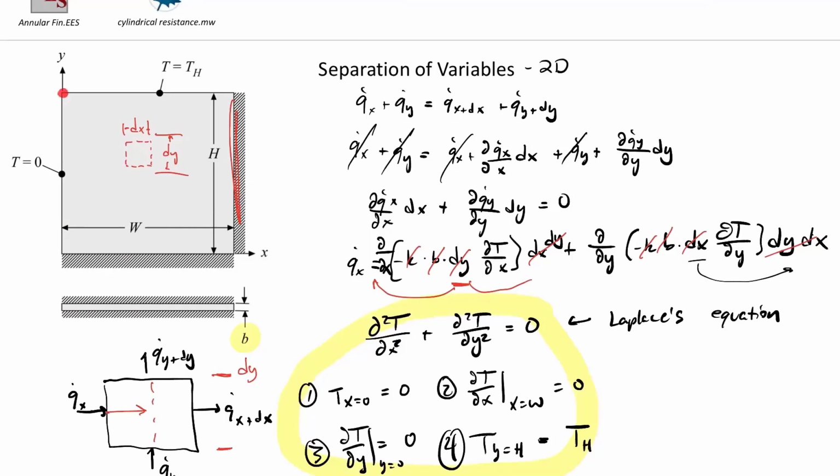We're saying the temperature is simultaneously 0 and TH at that corner. So you would write the problem this way so that it's a solvable problem for separation of variables, when in reality there's something going on here that is not purely constant temperature, right? But you'll see there's a discontinuity in the solution right at that point.